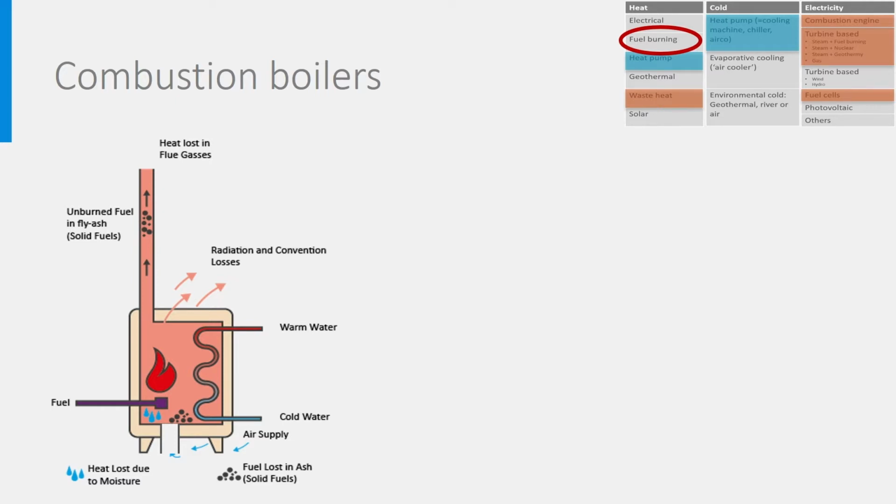In a condensing boiler, an additional heat exchanger is placed, see here above in the exhaust pipes for the fumes, which gives now also their heat to the cold water. Not only the fumes give heat back, but mainly the water vapor contained in the fumes gives a lot of latent heat when being condensed along the heat exchanger. Of course, these droplets of condensed water must be drained out of the boiler through an additional pipe.